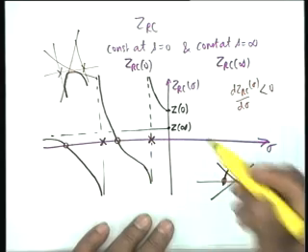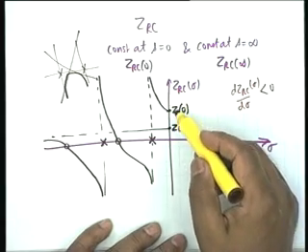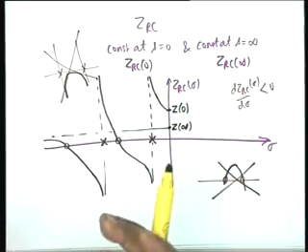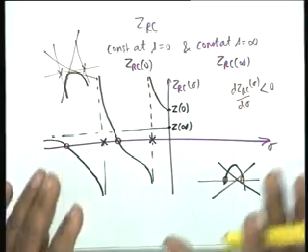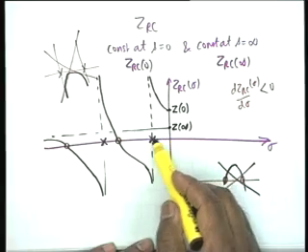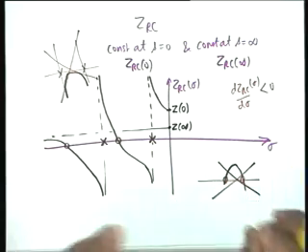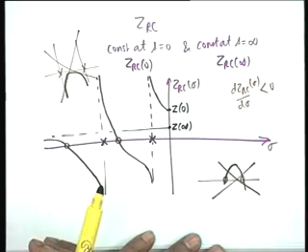One might argue that this is not the only situation. The function could have a pole at the origin. The behavior at the origin has only two possibilities: it might have a pole at the origin, or it is a constant at the origin. If it is a constant at the origin, then we see the first critical frequency is a pole. If it is a pole at the origin, obviously the first critical frequency is a pole.